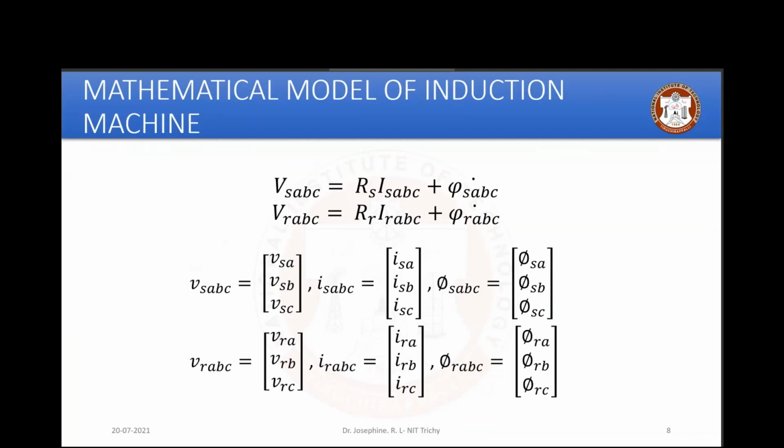But in order to understand that, prior to that, you should be able to simulate at least one mathematical model of the induction motor, I mean any electrical machine. So for that, let us enter into the mathematical model of the induction machine. This is a basic equation, like the source current in the stator, and rotor. If you take only the stator, it is RsIs plus L d phi by dt.